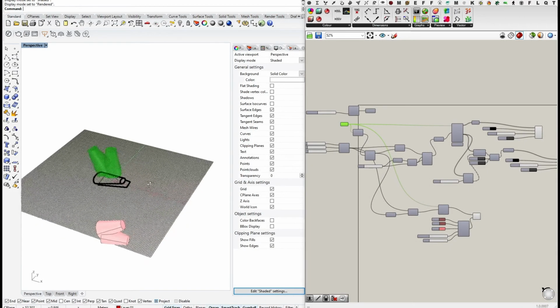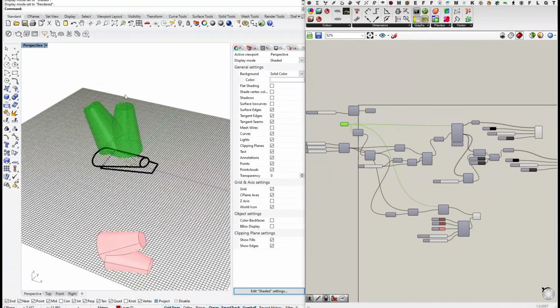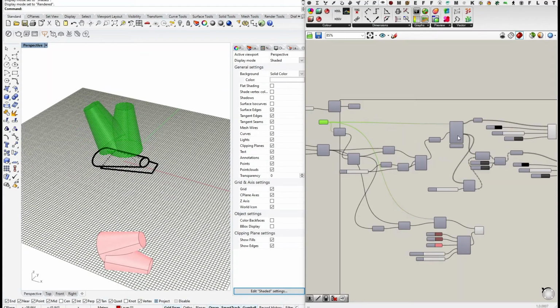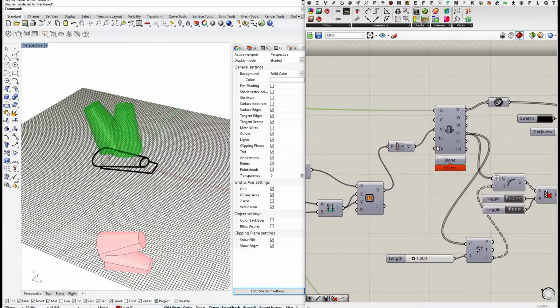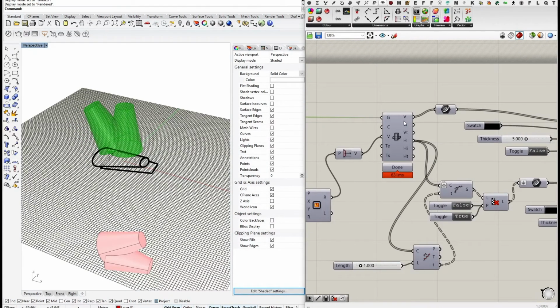The reason is that every time our base geometry is re-evaluated with the Make2D component, the sorting of these elements in the Make2D component changes. So we cannot rely on the list order of elements that is the output here, because sometimes it will generate more lines, sometimes less lines. And so we cannot say, okay, curve 1 will always be edited like this.